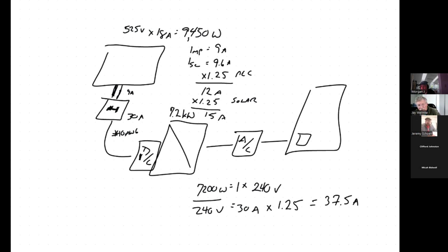We look at our table there on 111 and we decide we've got to put in 8-gauge wire, right? Yep, because it's rated to 40 amps. So now my AC disconnect, is it 30, 60, or 100 amps rating? Well, which one would I need?